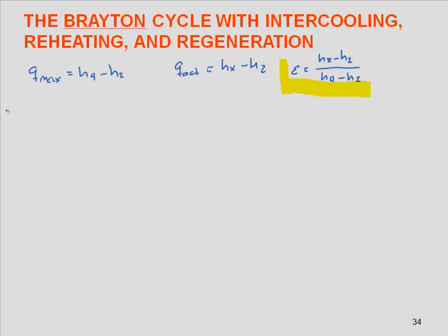let me change the color so you know there's a difference. For intercooling, we discussed in Thermal 1 that cooling the air during the compression will reduce the amount of work, since it will approach a reversible compression. It will approach an isothermal compression. But sometimes it's not practical to do it.